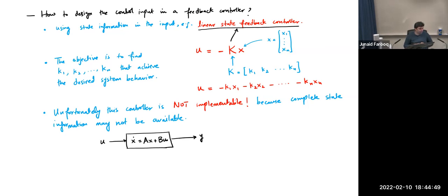You don't know where the car exactly is at a certain time, but you know the dynamics. So the exact state may not be visible. You cannot assume that you know the state and that it can be directly fed back into the input. There has to be some measurement device that knows where the state is. Even if you know it, there may be inaccuracies, there may be delay in the input. So a state feedback controller is not a viable option when designing a feedback controller.